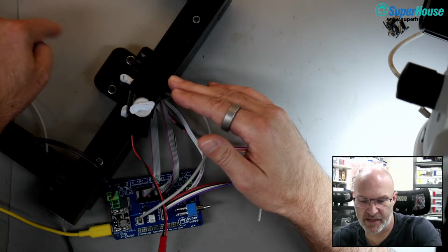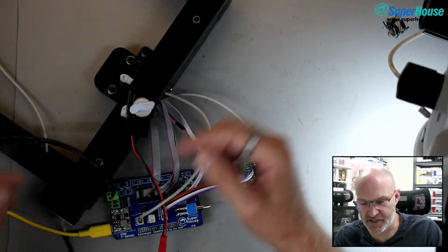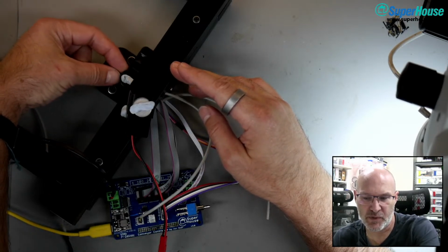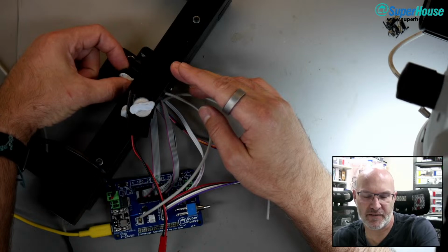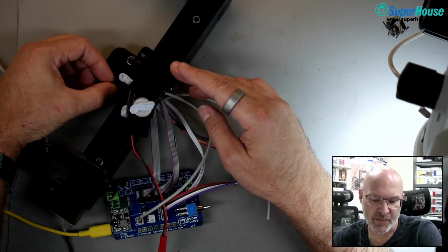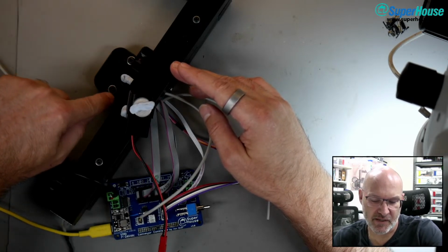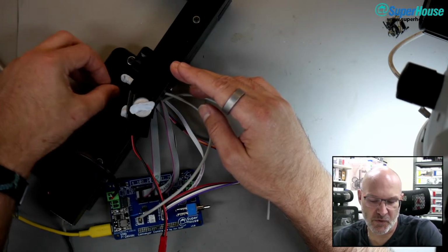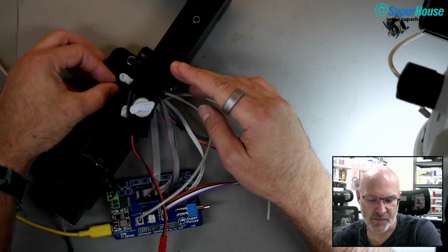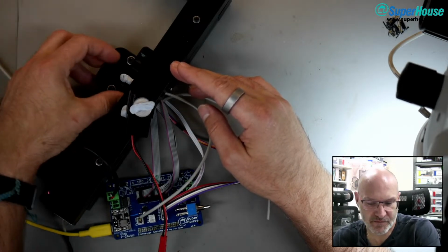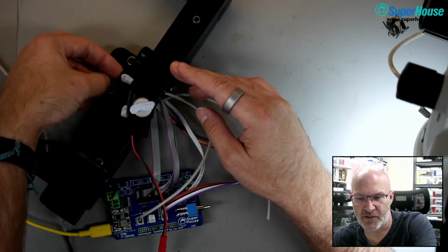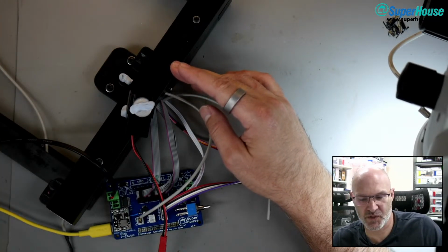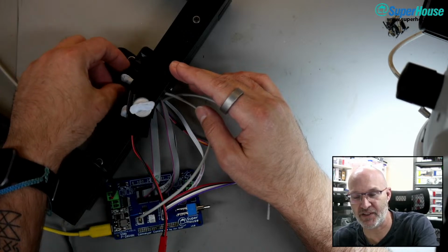So the belt goes around that. The belt goes around this little drive wheel on the stepper, and you can see it's flopping around at the moment. That's because it's an adjustable tension. There are slots here in the enclosure. So what I do is I drop the belt on and then slide this forward and then do up these bolts, and that just puts the tension on that drive belt. But the drive belt would end up just skipping on this and no permanent damage would be done. Worst case, maybe you've got to replace the belt if it tore it up.